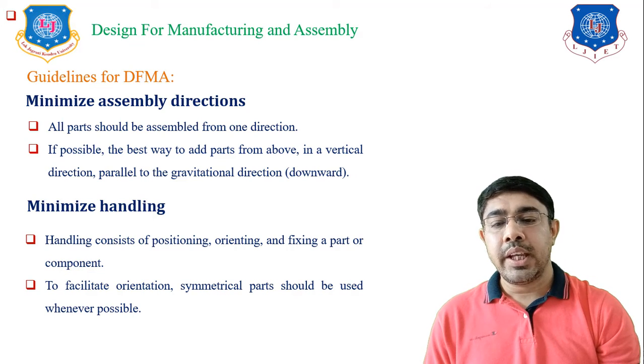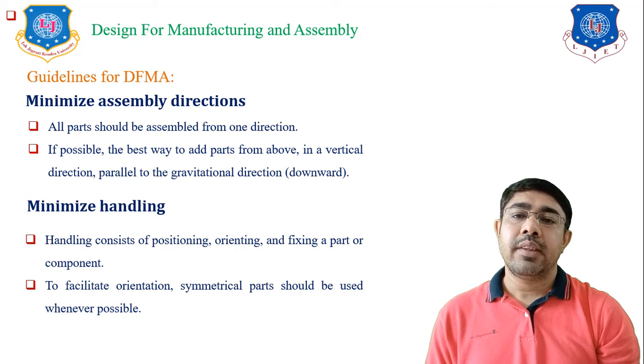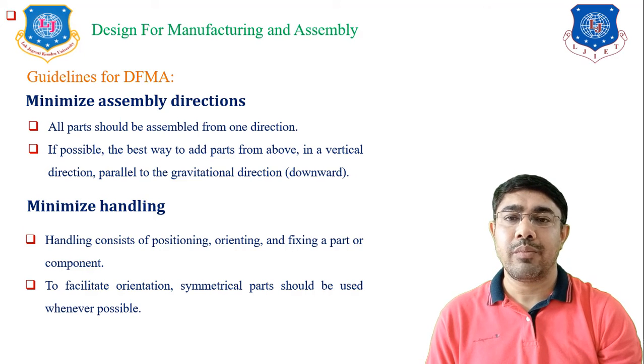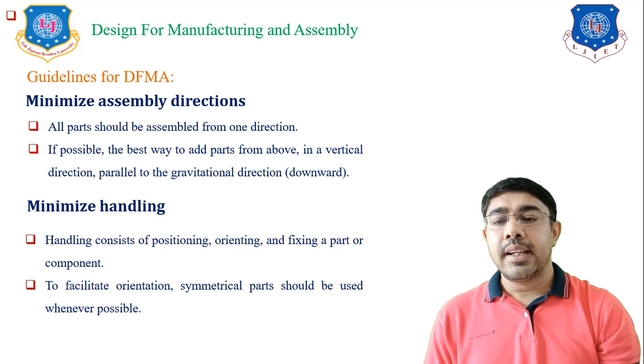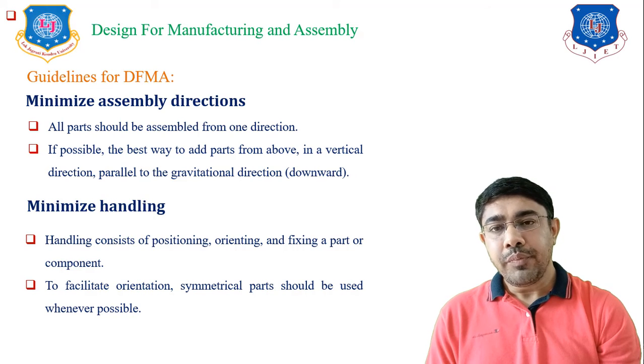To facilitate orientation, symmetrical parts should be used whenever possible. If there are symmetrical parts, we can easily orient those parts when we do the assembly of those particular components.